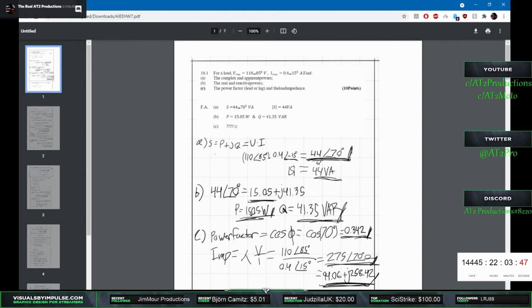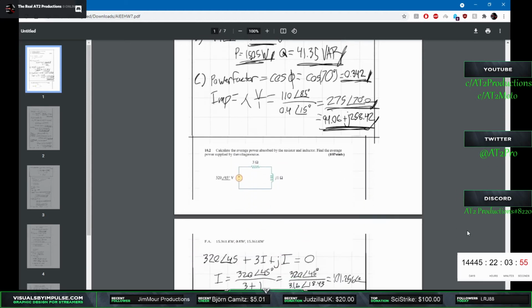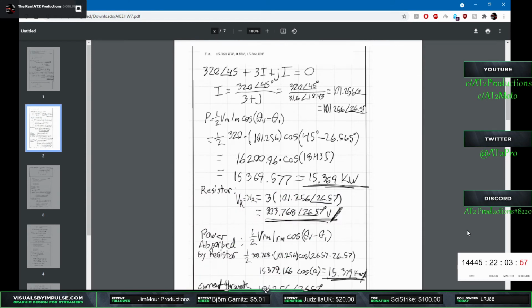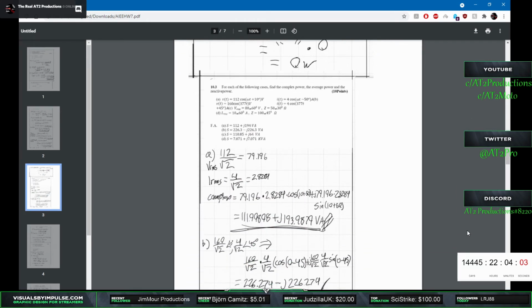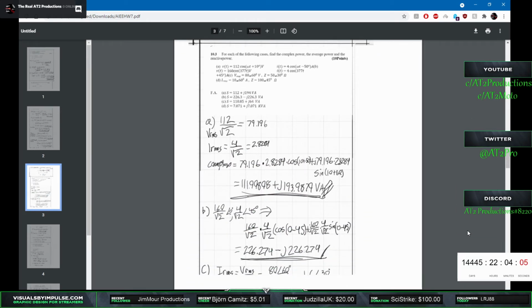But yeah, this is the fun shit that I've been doing all day while the rest of Twitter and YouTube are exploding. I spent most of my day actually working and trying to problem solve why an energy system kept spiking its DC portion from about 670 volts up to damn near 1,000. What I found is the problem: a dynamic resistor across the DC bus.